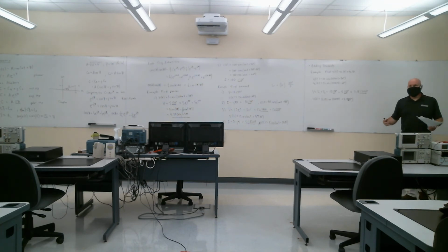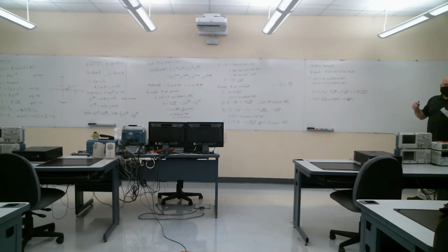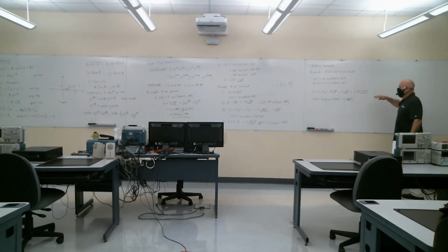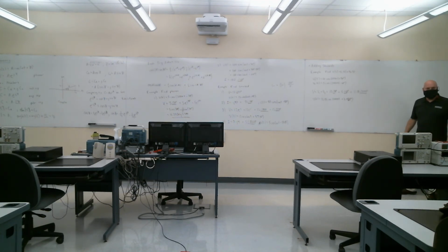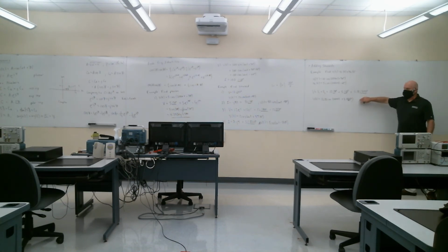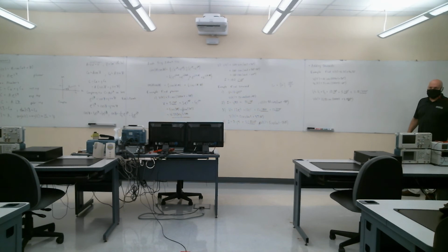Well, Kirchhoff's voltage law requires us to add voltages around the loop. The voltages in a loop may have different amplitudes and phases. They're all going to have the same frequency. And so instead of trying to sum all these time domain sinusoidal expressions with a bunch of trig identities, I can just add the corresponding phasors, convert back into the time domain, and I've got the right result. Makes things really simple.